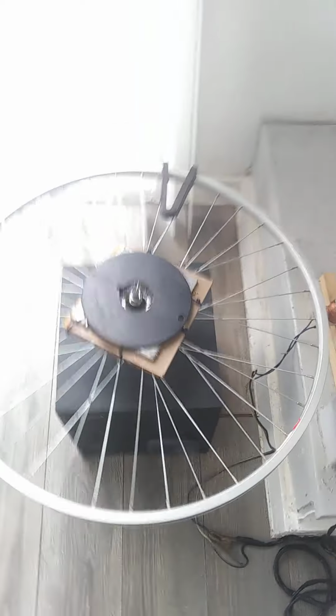The discharge from the coil is triggered by collapsing the coil field by earthing each coil at the correct time by the timer, or the commutator, mounted in the end of the camshaft on the front of the engine. So that's your timer.